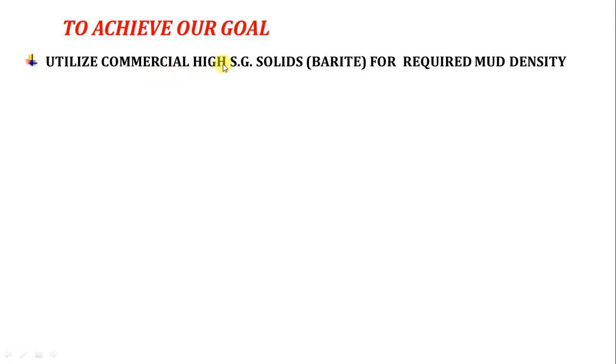So how can we make a solid analysis to achieve this goal? What we can do is utilize commercial high gravity solids like barite, for example, for the required mud density. What does this mean? Sometimes the mud engineers don't want to add barite, but they will tell you we keep drilling and the solids will increase the mud weight. Actually, this is a very wrong idea because it will increase the mud weight, but you have bad solids. You have too much drilled solids. You have cancer in the mud. So this is not a good idea. You have to drill and keep the only weighting material to be the barite or something like this, or take all your weight from the high gravity solids.